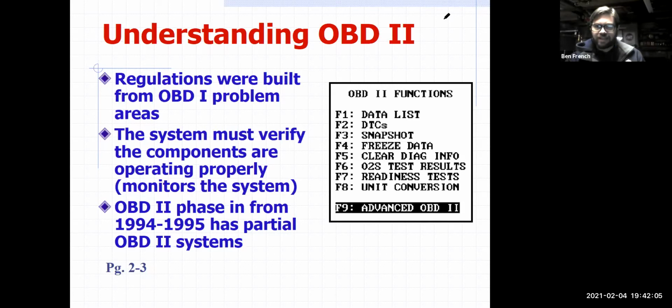They said, okay, we want you to give the technicians the ability to pull trouble codes from the computer. Okay, so that was one of the modes. And then they said, we don't want just codes. We want you to be able to look at data, certain data parameters, certain data PIDs, so you could see, okay, I got this code. Does the data support that code? Okay. Now this third thing was totally kind of new for OBD2.